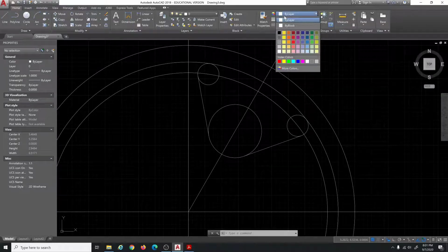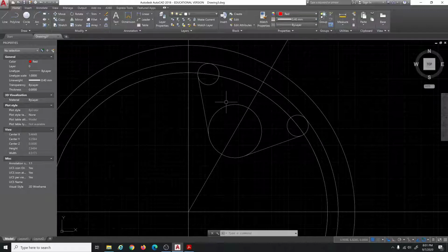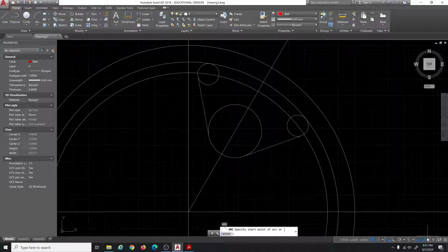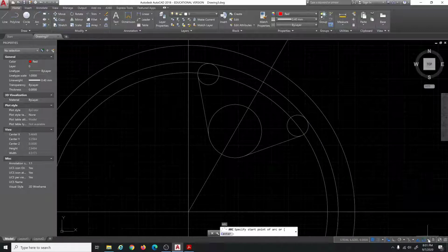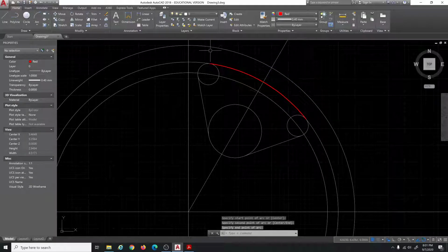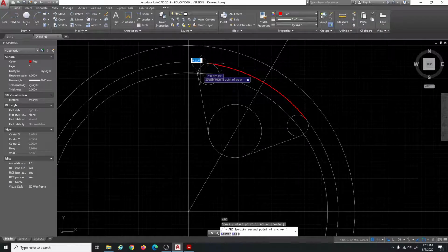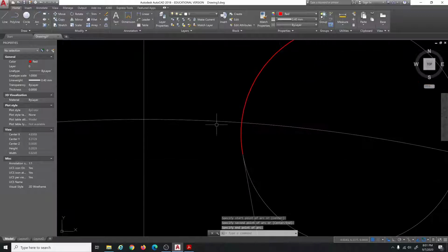Okay, then let's go ahead and heavy over this thing. So we'll go to red, heavy, and I'll start an arc. Okay, turn off the tangent snap, and now I just want intersection snap. So start, midpoint, endpoint. Okay, then enter to repeat the arc command again. There's start, midpoint, and then there's an endpoint here. Okay, got to make sure you're getting the right ones in there.